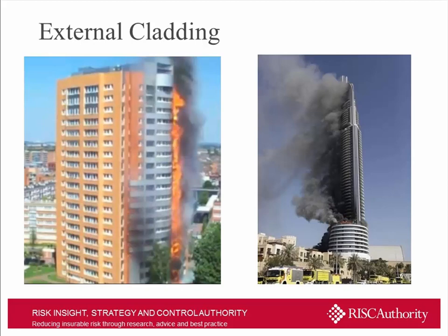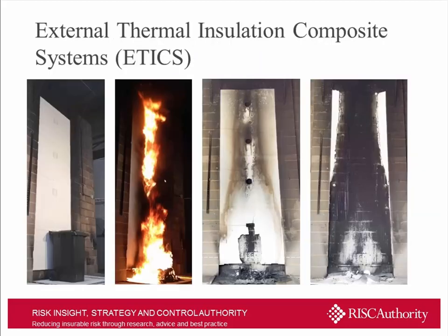Again, the problem with the use of combustible materials to clad and thermally insulate the building externally is that they won't only spread the fire up, but there's a potential for burning droplets and suchlike to fall down and start fires beneath the initial source of ignition.